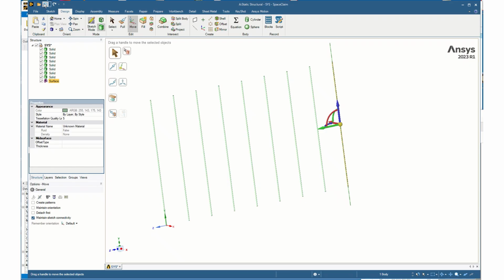So I'm going to come back here and undo that, and now I'll just click on the solid here, and I know that I have the solid. I can hit my control, grab the axis, and move this 500, enter. And now I have all of those, and I'm ready to start to create the beam.